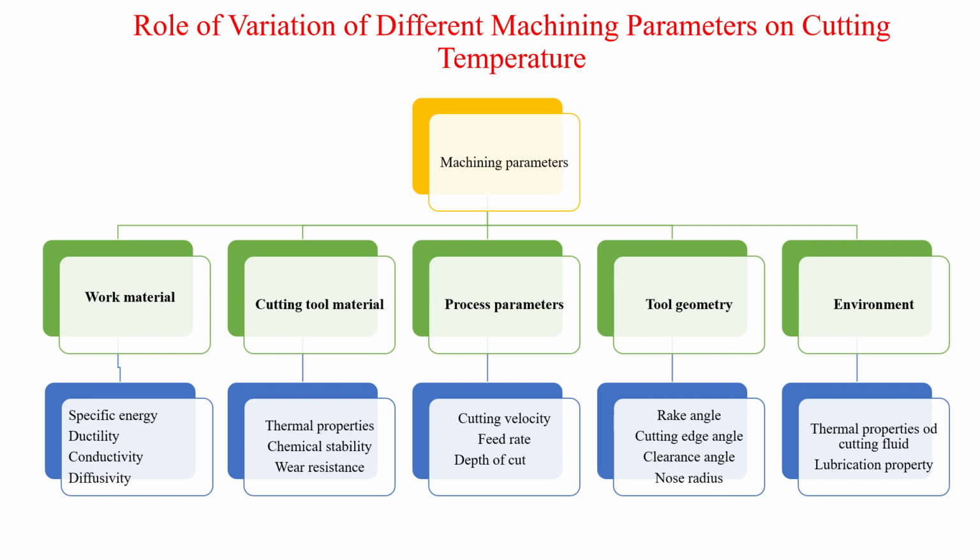And then comes the environment. What cutting fluid are you using? What are its thermal properties? What are its lubrication properties? All these factors need to be understood very thoroughly, so that we can study the variation of these parameters with the temperature. Okay, now we will see each and everything in detail.